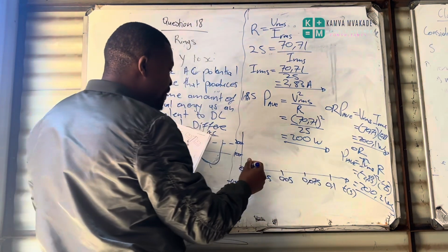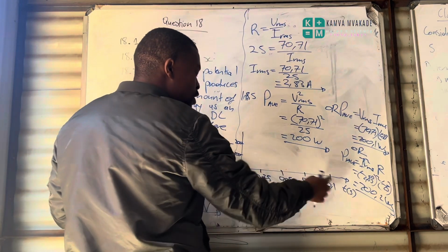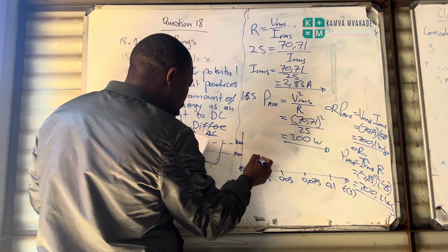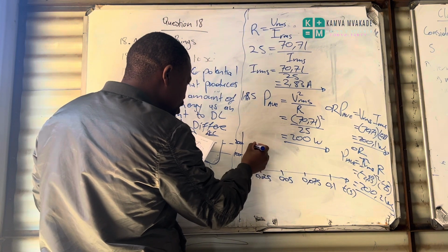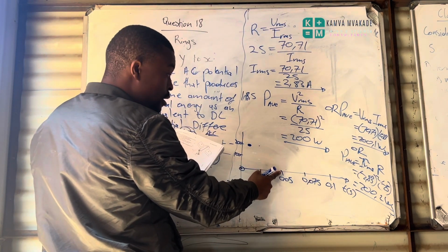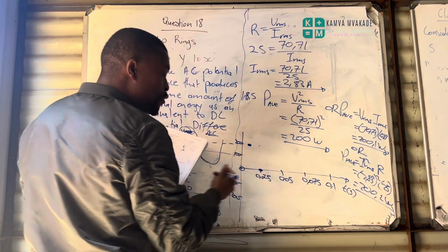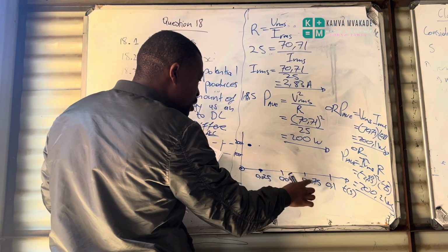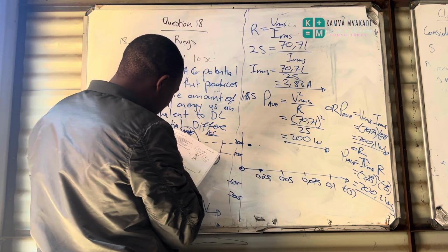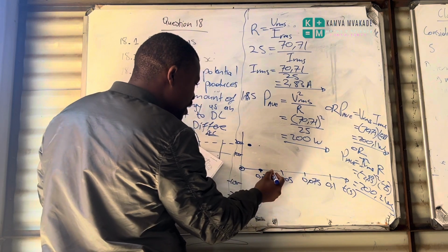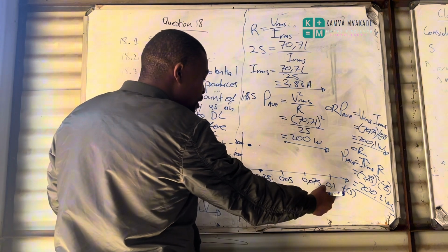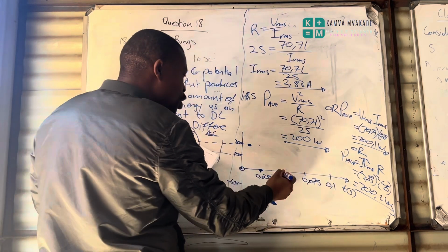The graph here: the period is halved. So the voltage reaches 200 at 0.025 seconds. At 0.05 it goes back to 0. At 0.075 I get the next point, which is negative 200. Then at 0.1, it returns to 0 again, completing two cycles.